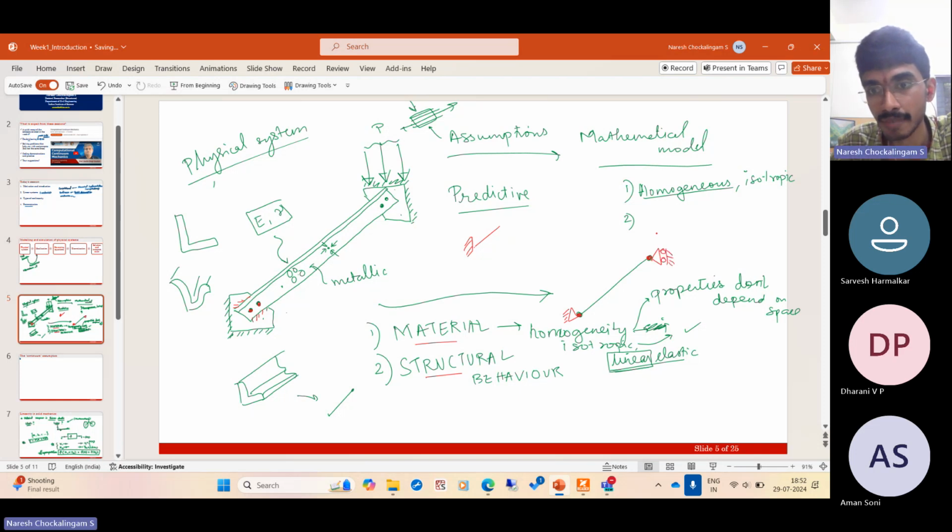You allow vertical displacement on one side, and because this is loaded, right? So we have some loading here. Here it should allow some vertical displacement, and horizontally you can. So this idealization really depends on the actual field conditions, what kind of connections we have, and so on. So the third idealization is boundary conditions, support conditions, or boundary conditions.